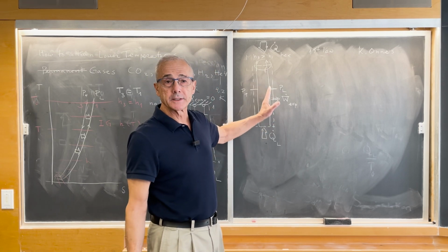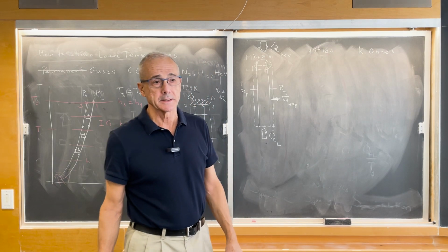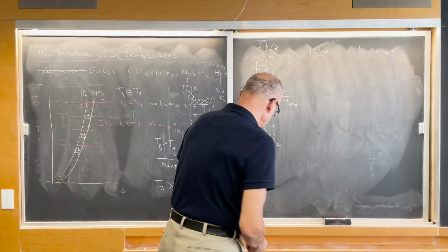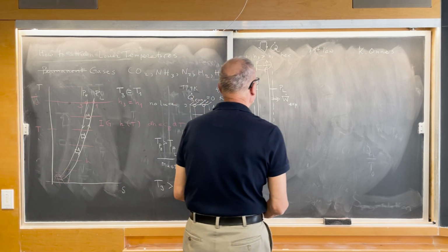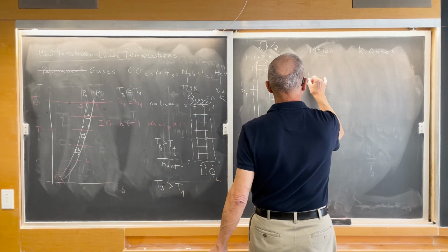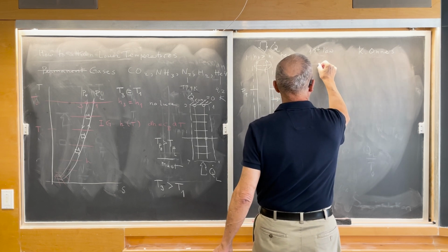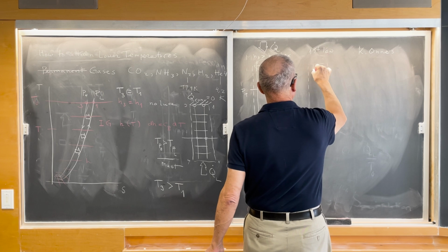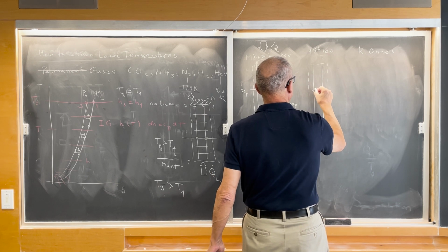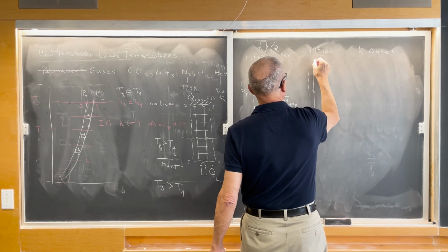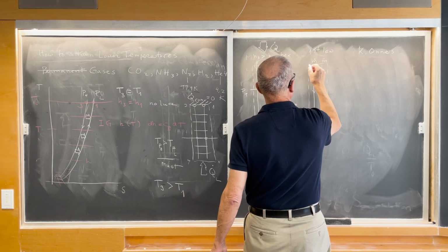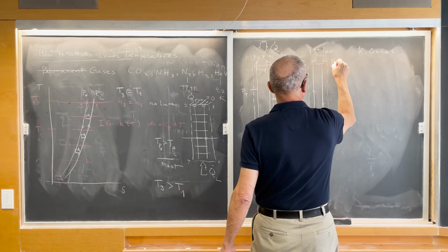Anyway, this is the way to remove these heat transfer rates out of a box for which the heat transfer had no exit. And the technique, which I will sketch now in red, is to, in fact, let me draw the box one more time here. This is the counterflow heat exchanger. Then the mass flow rate is the same on both sides. Here is pH, pL.